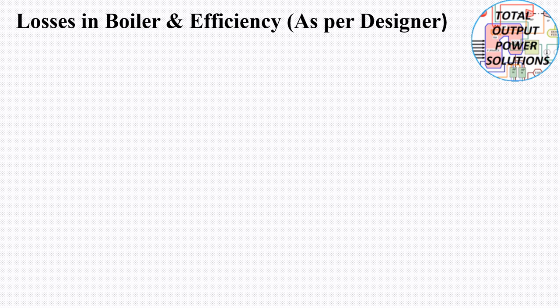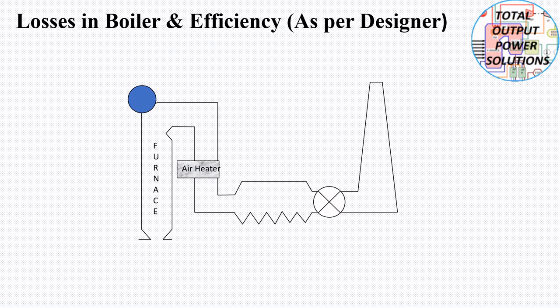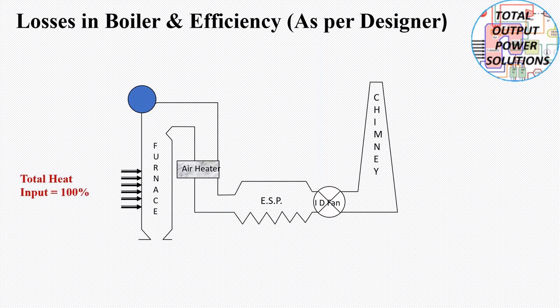Now, here the ash is the product of combustion of pulverized fuel, that is coal, inside the pulverized fuel furnace. So when coal is burned totally, the ash will be formed. But somehow, though the coal is pulverized in the coal mills and then burnt in the combustion chamber of the boiler, it does not burn fully, and you get unburns in the bottom ash as well as in fly ash.